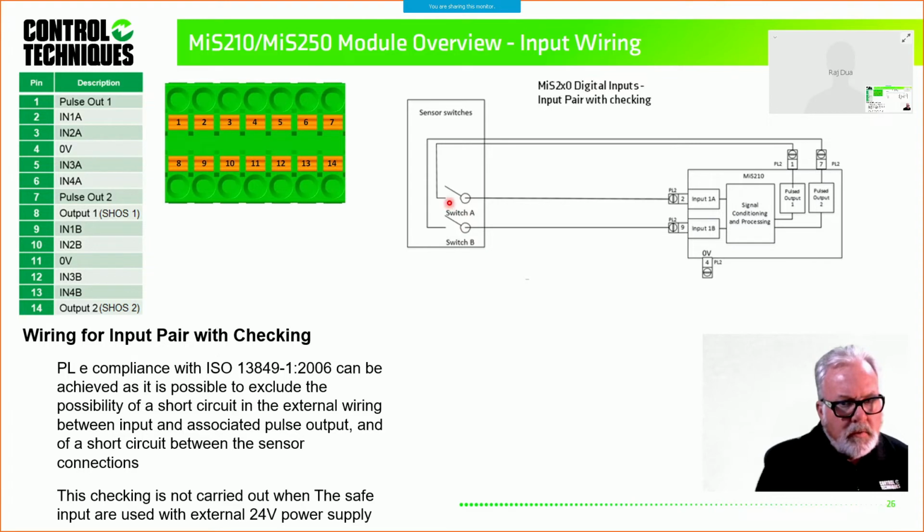When it's closed, it's off. So when it's closed and using these pulsed terminals, the controller here will send a low frequency, low voltage pulse train all the way through this circuit to check the integrity of the circuit itself. So using the pulsed outputs is just an added layer of safety. Now, I did not do that in my demonstration, but know that that's what the pulsed outputs are used for.